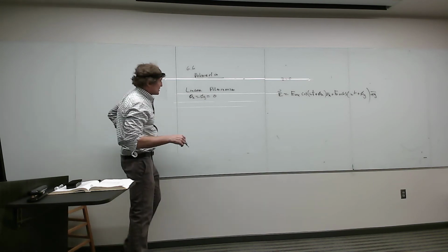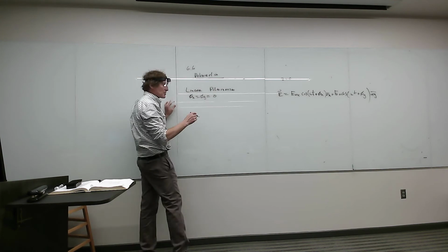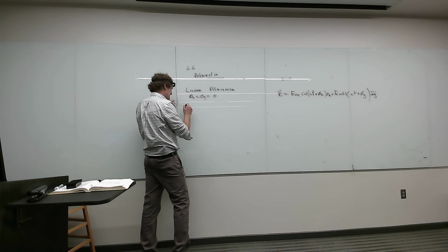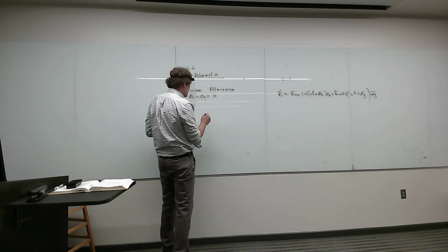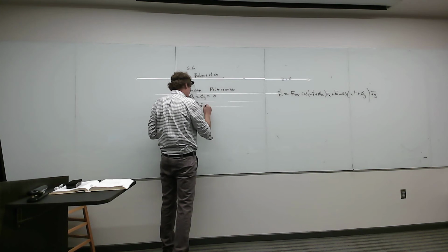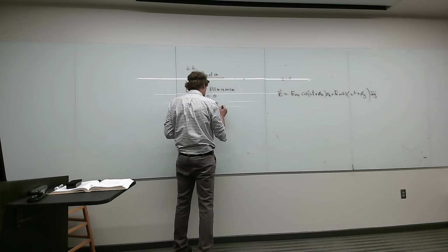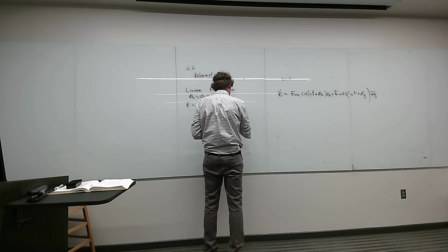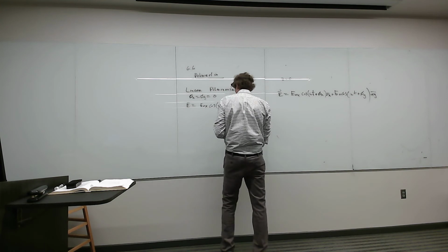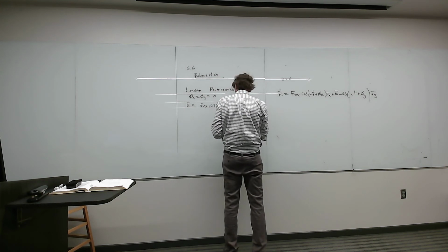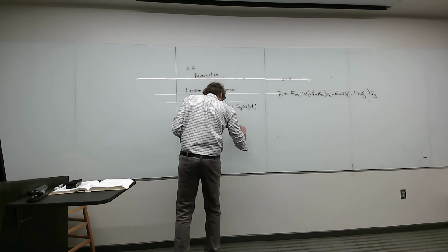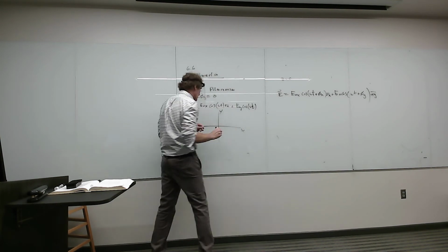All right, look, when you have this, take a look at those equations and what happened. I'm going to do linear, and I'll do elliptical, or we can do circular too. But if you look at this, what happens? I get an E field here equal to simply E naught x times cosine of omega t ax, plus E naught y times cosine of omega t right here. Now just take a look at that for a minute and plot some points in your head. Here's x and y. Remember, we're at z equals 0, right?